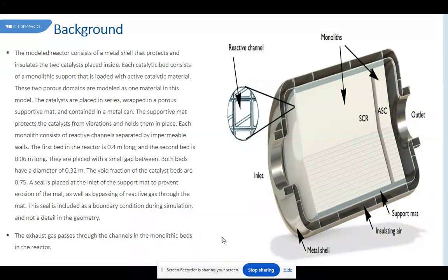When the 400 per 6.5 monolith was placed at the core, approximately 60% of the flow passed through it. On the other hand, for the opposite case, where the 400 per 6.5 was placed at the ring and covering the same 50% of the transverse area, only 36% of the fluid passed through the section. Such a value is lower than the 40% expected if the curves were the exact reciprocal.